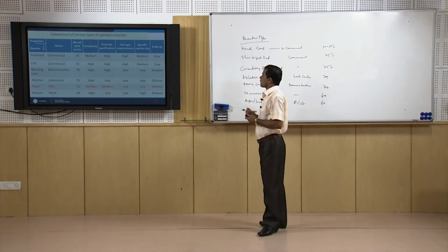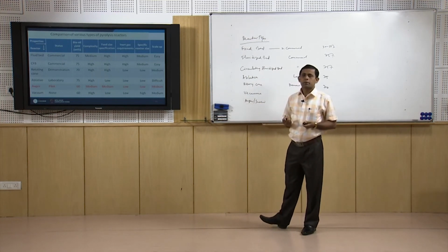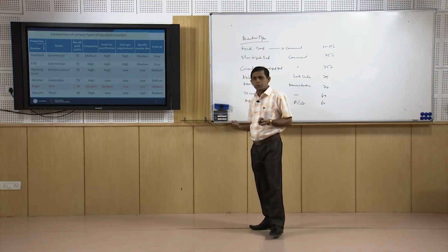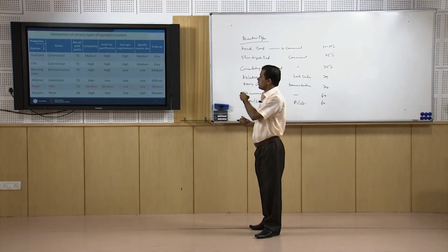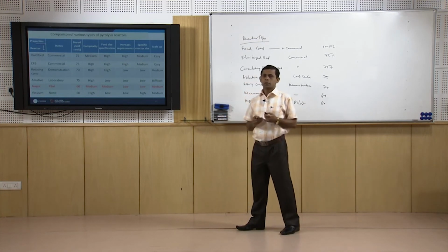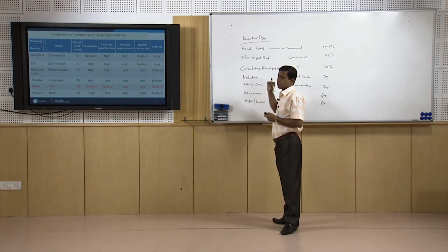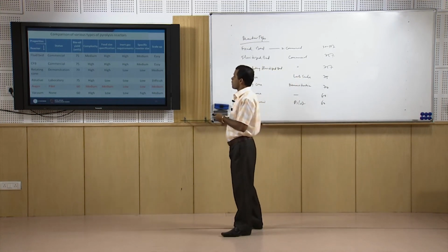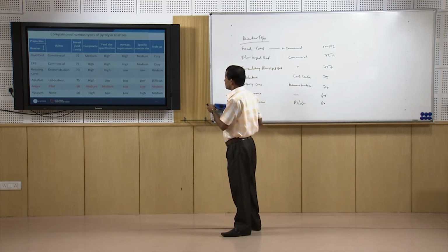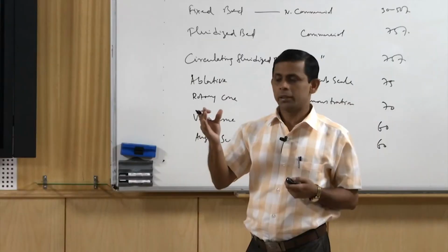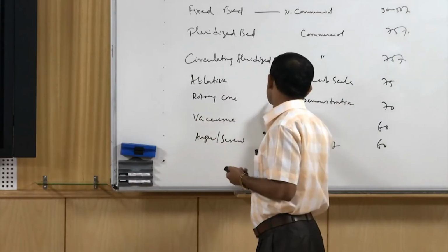If we think about ease of scale up, obviously fluidized bed is easy to scale up, CFB is easy to scale up, but ablative is very difficult, and auger is medium. Screw reactors are also not so easy to scale up, but it is medium, it can be done. Regarding feed size specification, fluidized bed is highly specific, the particle size should be less than 2 millimeter.